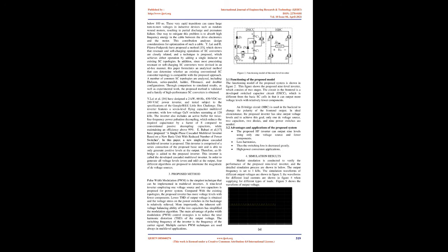There are many limitations with the traditional boost converter in simultaneously achieving high voltage gain with high power density and efficiency. Some of the major limitations with these systems are high voltage stress on switches and diodes, high conduction and switching losses, and large magnetic volume due to the low frequency switching of the required high voltage switches. The switched capacitor, SC, converter is another type of converter that can attain large step-up ratios. It utilizes the high energy density of capacitors to transfer energy, resulting in much higher power density than conventional switched inductor DC-DC buck or boost converters.